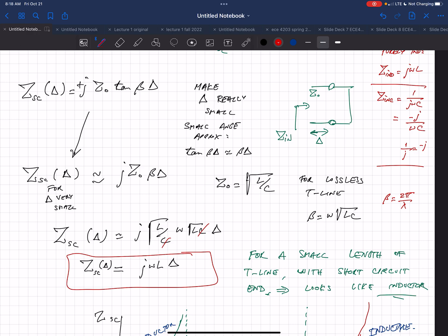That means if you're poking along the line, you're going to see voltages that look like they're just sitting there and not moving, like a wave. It's almost like you've frozen the waveform of a combination of forward traveling wave and backward traveling wave. Okay, that means if you change the position where you're looking along that transmission line at those voltages, at some point you're going to get repetitive patterns.